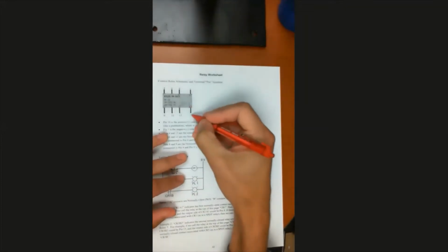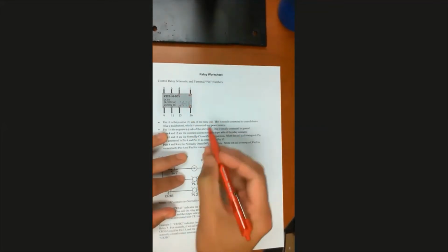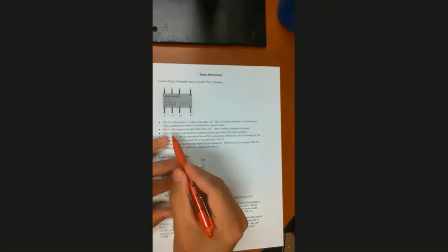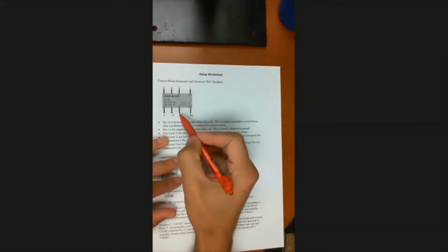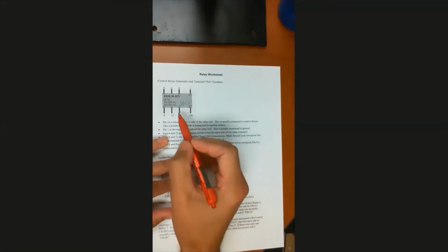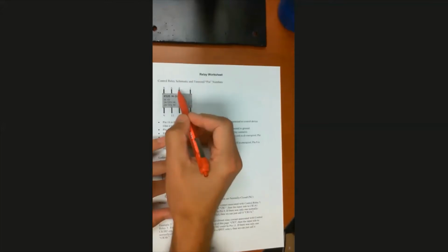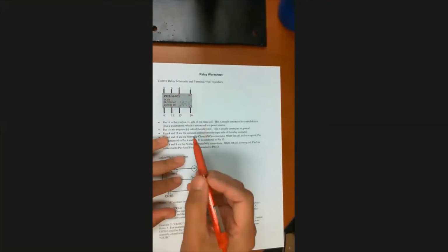So pin 16, that's the positive side of the coil, and pin 1 is the negative side of the coil. That'll go to ground. And then pins 4 and 13, these are our common connections. Right? These are our inputs to our switches. 13 is the input to these two, 9 and 11. 4 is the input to these two, 6 and 8.